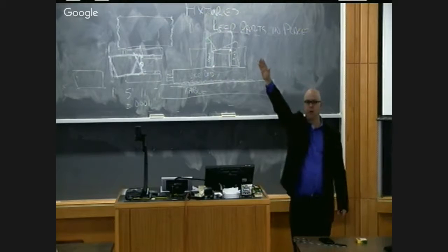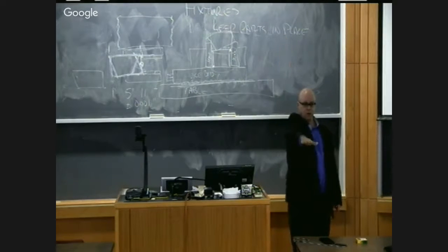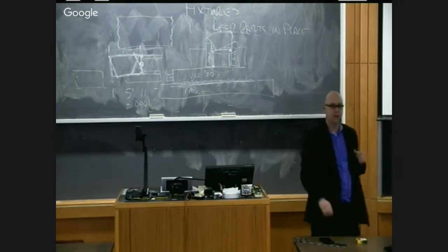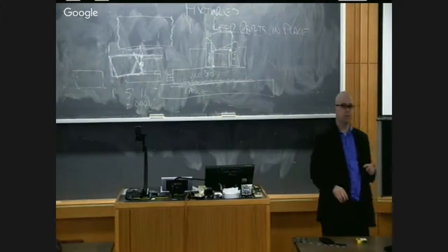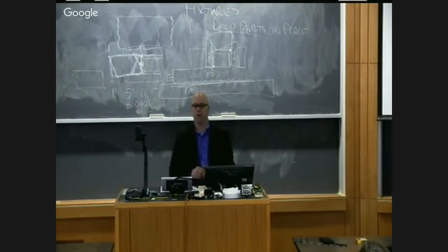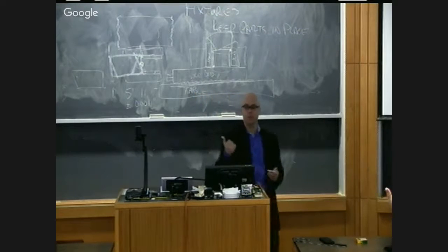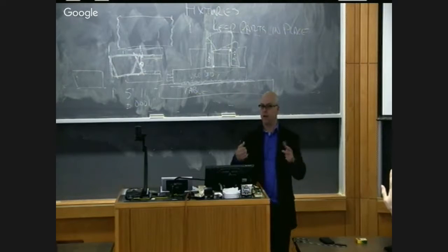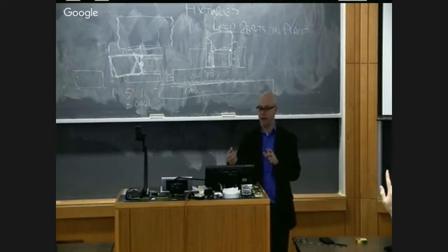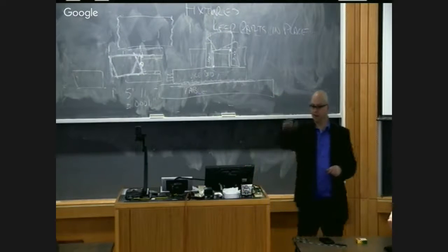And so we want to do a worst case scenario. We either assume the force is all the way up or all the way to the side along the direction that it can slide, right? And so what's our maximum cutting force that we can have? We can figure out the maximum cutting force, and then we can see what's the maximum power we want to allow. We could actually set those machines to stop, to alarm out if the power exceeds a certain threshold, and you can set the threshold.